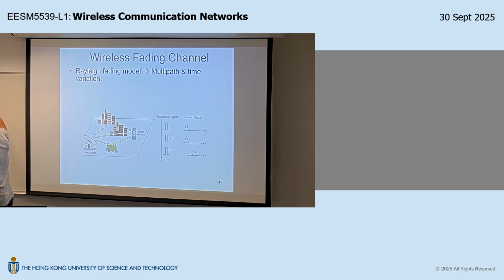So this gives you the received power density at any point on the surface. Agree? Now let's say at the receiver, I put up an antenna. The antenna has a certain aperture AE, which is the effective area. Then the received power is given by AE, this effective area, times this power density.